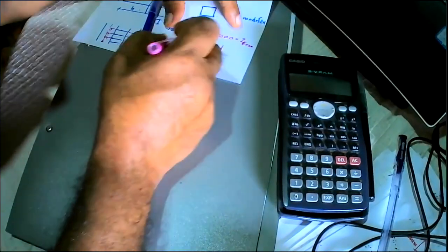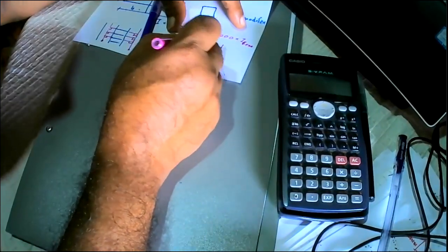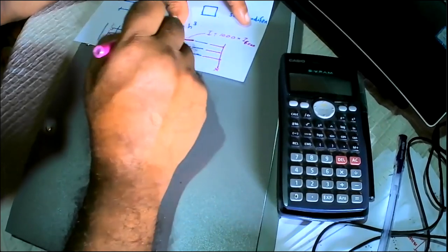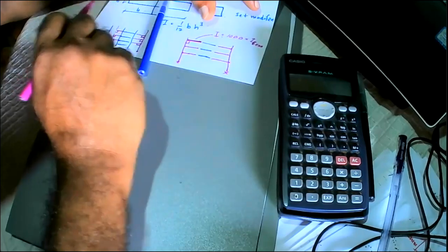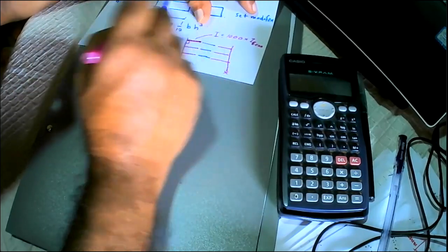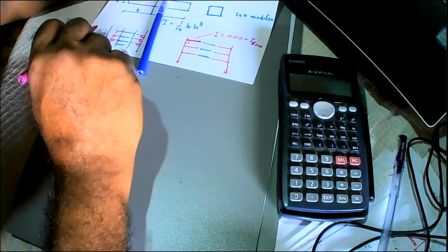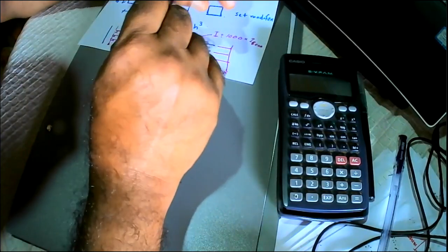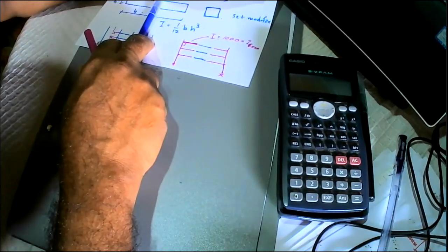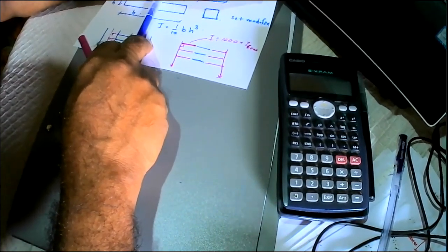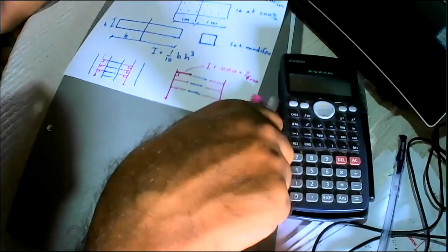So the idea of a rigid arm is that this arm is not going to deform. It is rigid. So you get 90 degrees before the deformation and 90 degrees after the deformation, and over the length there's no deformation in the arm. So this way, if you want, you can represent the walls as columns and then combine them with rigid arms. So these are some of the modeling techniques.